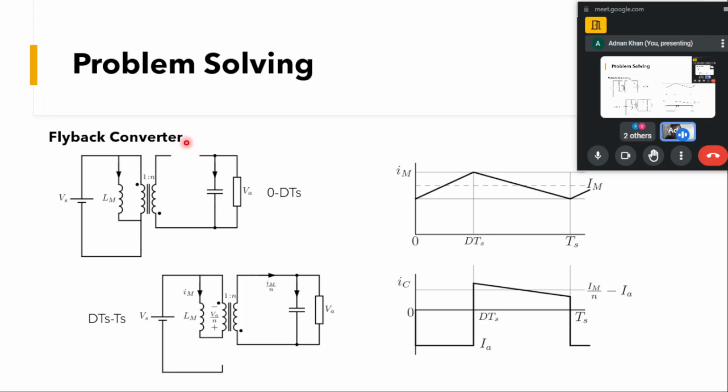This diode is reverse biased, so this will be an open. When this is open, no current can flow through the secondary side because the circuit is open on the secondary. When no current is in the secondary, there can be no current in the primary, because due to transformer action, if there is a current in the primary, some current needs to flow on the secondary side to balance it.